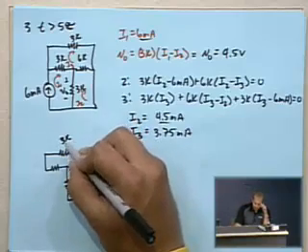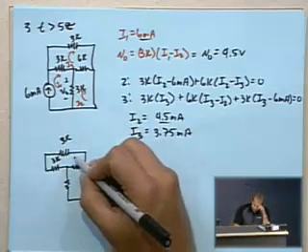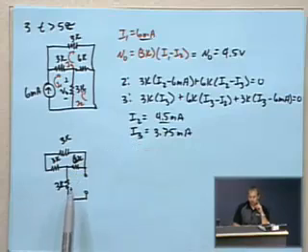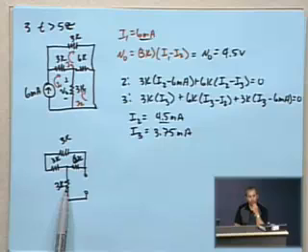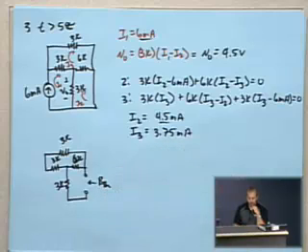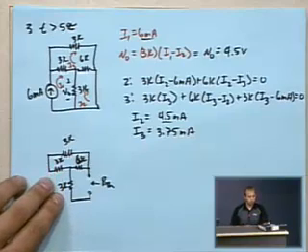One was to look at the Thevenin resistance from the point of view of this 3K resistor that we were finding the voltage across. You don't do that. You always look from the point of view of the storage element. So we're always looking in from here to find our Thevenin resistance. We also need to make sure that we properly zero out the current source: it doesn't get short-circuited, it gets open-circuited. So there's just a hole in the circuit.